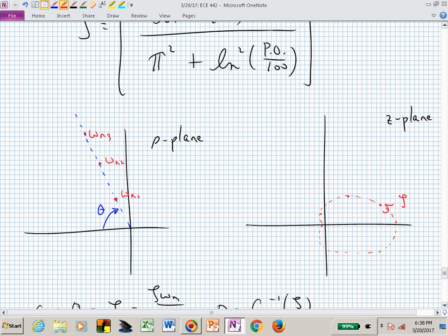And if I want more damping, what do I want my zeta to be? Bigger or smaller? I want zeta to be bigger. I want zeta to be growing or getting closer to 1. What do you think zeta equal to 0 gives me in this z-plane plot? Zeta equal to 0 gives me what shape? How does this heart distort when zeta is equal to 0? I have zeta equals 0 has how much damping? Zeta equals 0 is where in the S-plane?